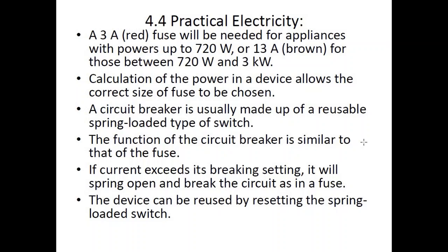A 3 ampere fuse will be needed for appliances with powers up to 720 watts, and a 13 ampere for those between 720 watts and 3 kilowatts. Now these are different ratings for different countries, so you don't really have to remember that a 3 ampere fuse is red, 13 ampere fuse is brown. Remember, if you have to calculate what type of fuse should be used in a circuit, then simply calculate the power of that circuit,